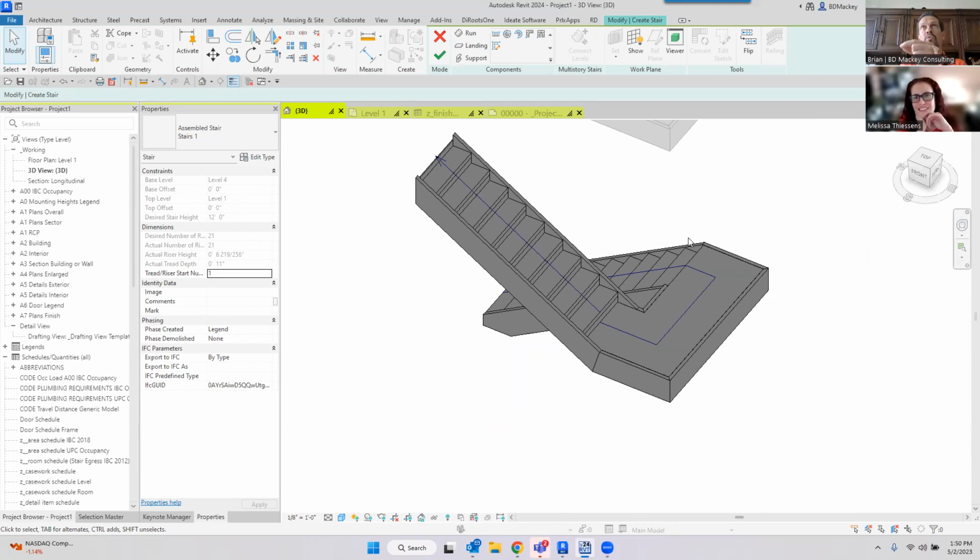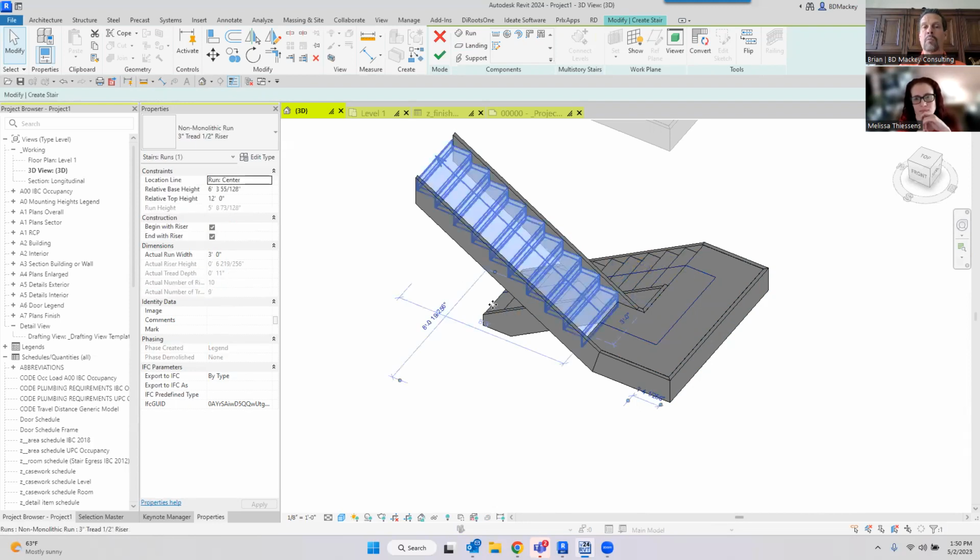The arrow shifts it to the previous run or the beginning of the current run. So if I were to grab that without deleting the landing and move the arrow here, it would add runs down here. If I had grabbed the dot and done it, the dot would have just taken some away here and I would have been 2 treads short. I could have just hit the move command and unmoved, probably would have been easier, and moved it 22 inches, but whatever.